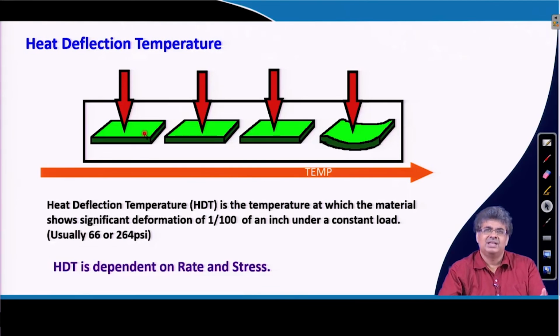Basically, if we use a polymer under some load, then up to what temperature it can sustain that load is more important than the Tg or Tm value for the inherent polymer. And of course, in that case the temperature up to which it can sustain the load will depend on the load itself, and the higher the load is, obviously the lower the temperature will be.